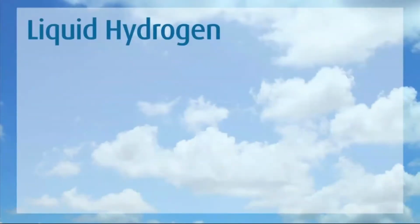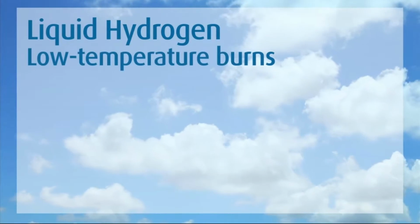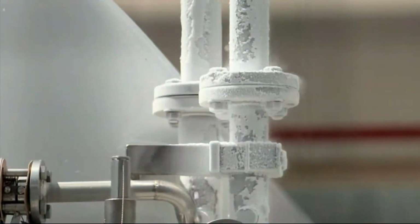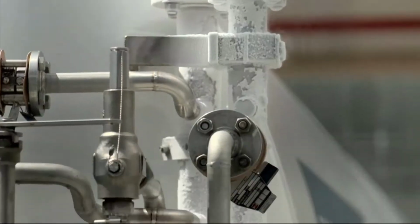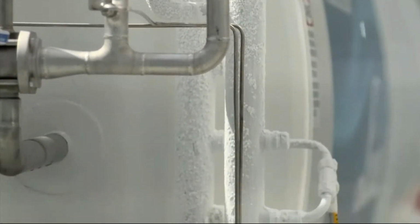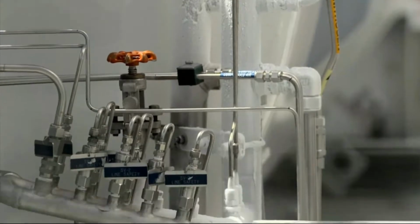As we said earlier, liquefied hydrogen is one of the coldest materials on Earth. At 423 degrees below zero Fahrenheit, this presents a tremendous risk of low temperature burns. In this respect, it's even more dangerous than liquefied nitrogen or CO2. Workers should never touch liquid hydrogen pipes, valves, or other equipment with their bare hands. Even if their hands are dry, they'll stick instantly because the super low temperature of liquid hydrogen will draw moisture right out of their skin.